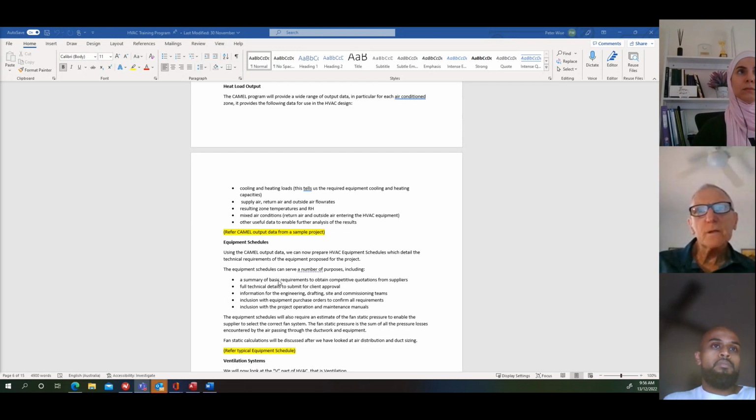At one stage in my career, we were doing D&C work exclusively, and we would be quoting a job nearly every day. In one year, I think we did 400 quotes for D&C jobs, so more than one a day. I'd always do a heat load, work out what equipment we needed, put it on a schedule and send it out so we could get prices for that equipment. And also for the fans, for the outside air, for the toilet exhaust, all those things. We need to produce schedules to get prices.